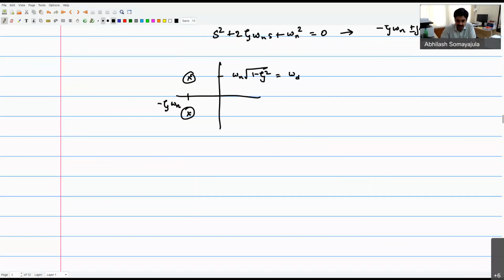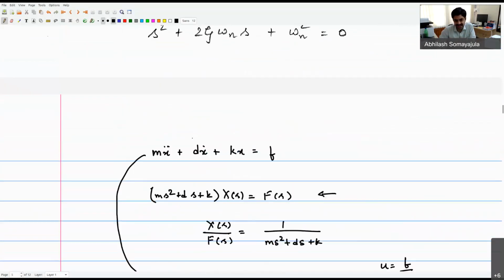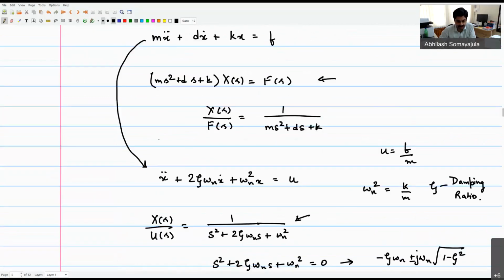Based on those specifications, you will figure out how far on the left side the poles should be such that these characteristics can be met. That part we are not discussing in this course, but it was discussed in your maneuvering and control course. Once we know where the poles are in the complex plane, the question becomes what Kp and Kd should be so that I can eventually drive the system to that location. That's the idea we were trying to look at.